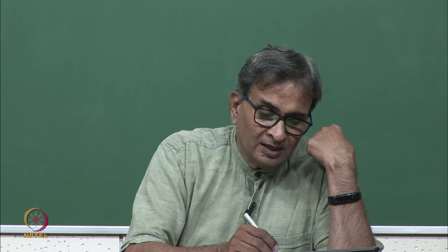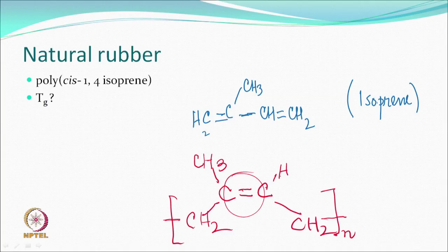So, you have to do some amount of vulcanization or cross linking, and it can be done because in the polymer you see there is a double bond already. Therefore, you can do some cross linking of the polymer itself. So, there is a rigid structure, because of that you get the cis configuration, and so you get from isoprene to polyisoprene. So, this is natural rubber, and it has been used for various purposes, including coating on textiles.